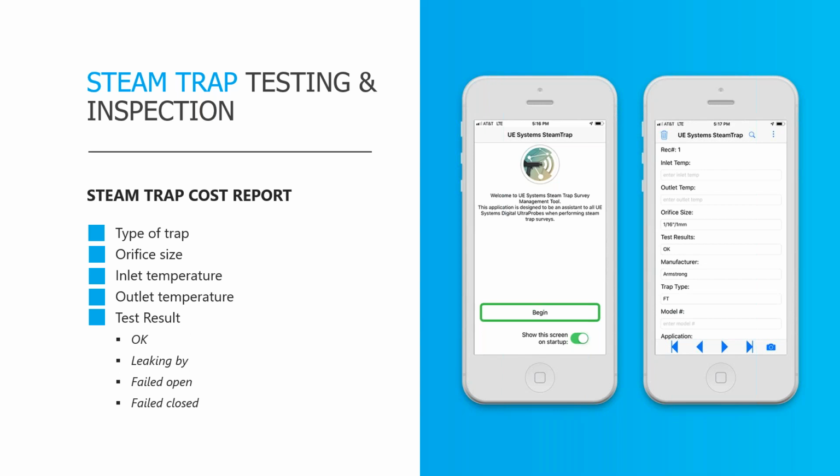Your float and thermostatic traps are not designed to cycle open and then shut. Your F&T traps will have a more continuous flow, but yet a modulating continuous flow type of sound. So typically on your F&Ts, you'll have an inlet up on your top. Then you have kind of this curved housing where a ball float sits at the bottom of that trap, and then you'll have an outlet just past that ball float.